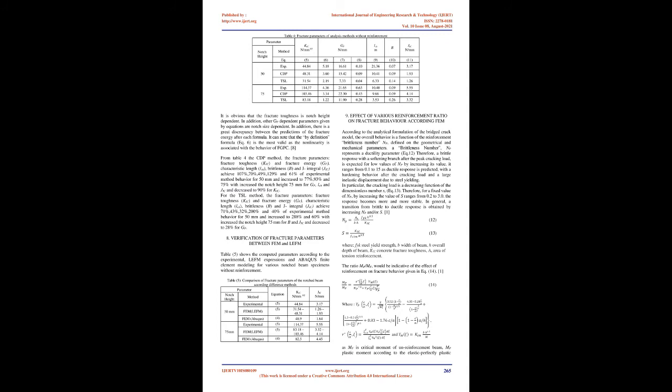Linear elastic fracture mechanics analysis, LEFM. Based on displacement control loading of specimens, fracture toughness, KIC, fracture energy, GF, characteristic length, LCH, brittleness, B, and J integral, JIC, were estimated. Development of the constitutive model for a material requires its fracture parameters, which were quantified analytically for cement concrete, Eq. 5, 17, 18 and 27, as follows.